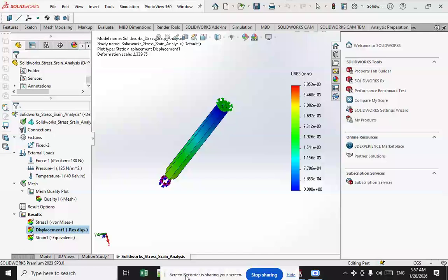However, if the system can be assumed to behave in a linear fashion with respect to the loading and response of the system, then the effect of preload can be accounted for by adding the results of the preloaded structure and the same non-preloaded structure.